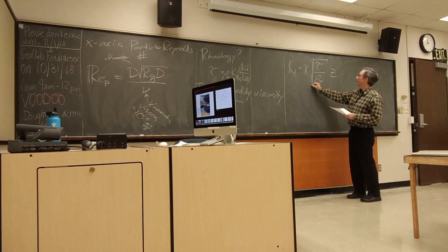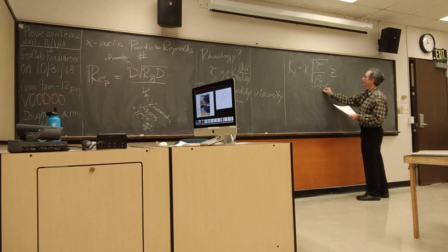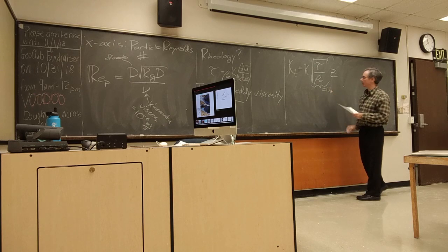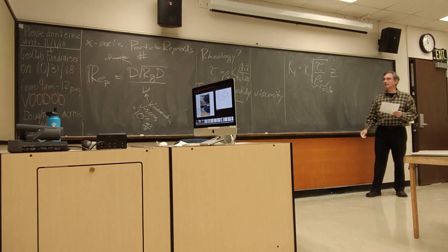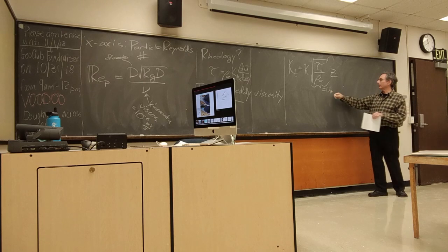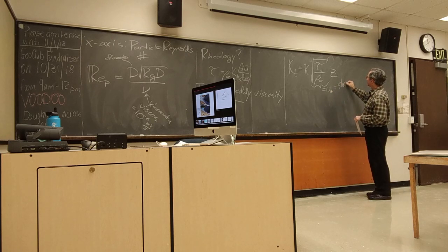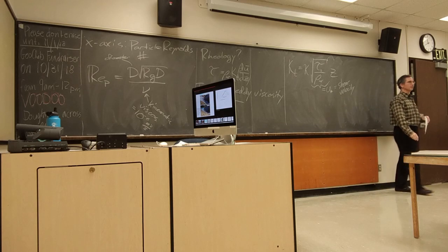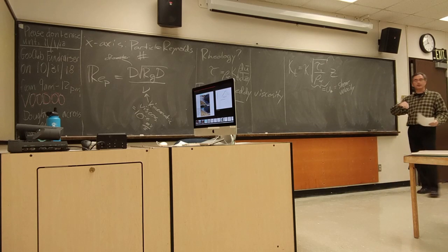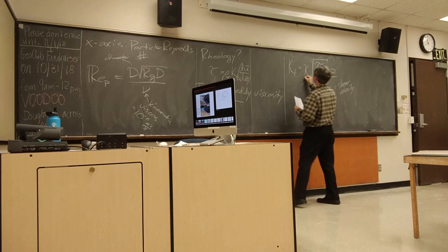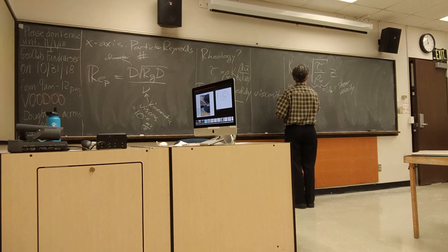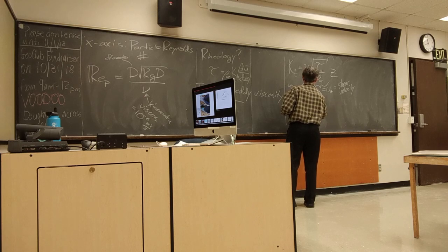And this thing, I'm going to define as a so-called shear velocity. This combination of shear stress and density has units of velocity. We call that the shear velocity. It is not an actual velocity of anything except by coincidence. It simply is a way to express the shear stress of water with units of velocity. This here is von Karman's constant, and it equals 0.4.